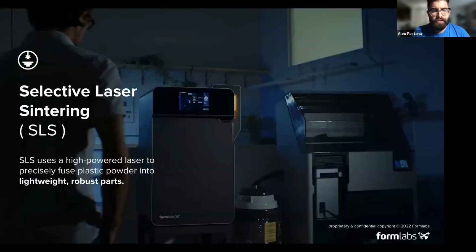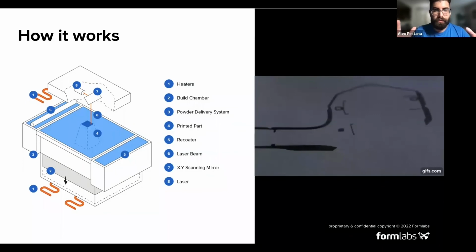So switching gears to SLS. SLS stands for selective laser sintering, as you could tell. It's in the family of powder bed fusion, which is generally anything that uses a powder, whether that's metal or plastics, and fuses it together by some means. For our process and for selective laser sintering in general, we're using plastic powders and taking them up to temperature. In our case, it's about 180 Celsius. So we're heating up that chamber of powder and then using a laser to melt the plastic.